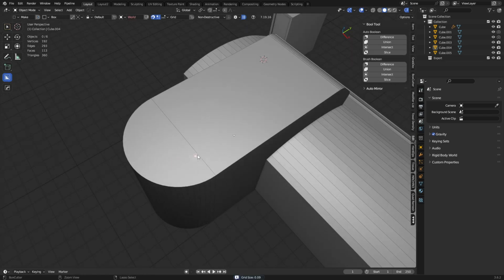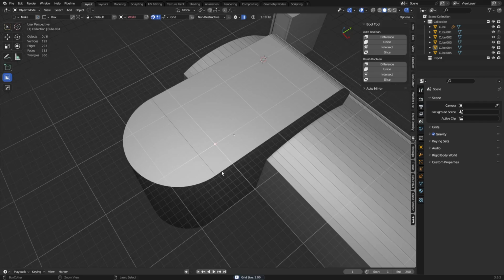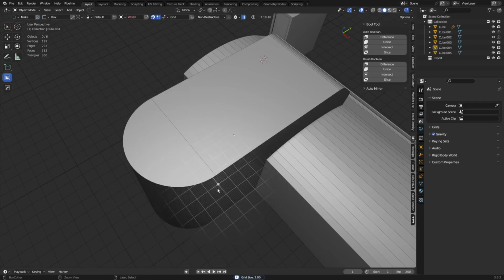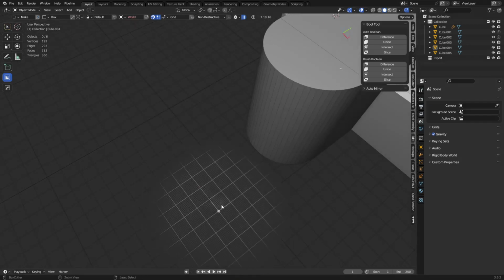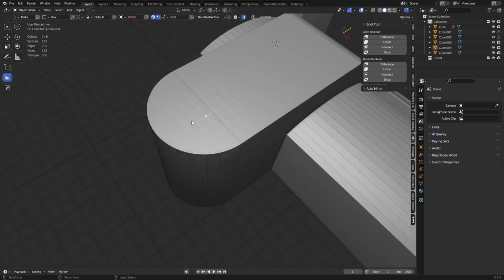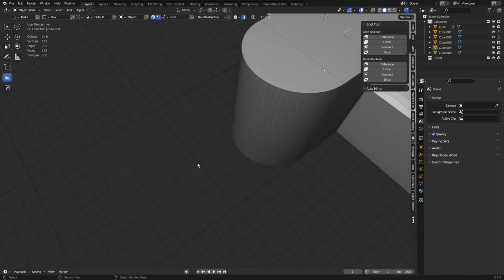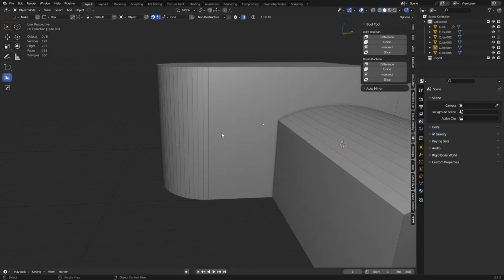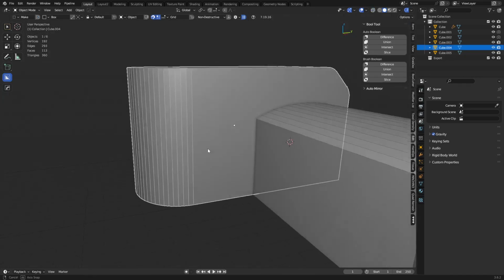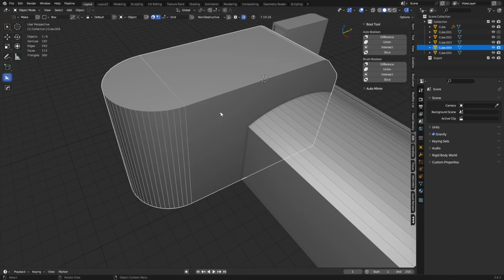And that is that the grid here has smaller grid sections, right? So if we set this to a grid size of 1, we already know it's going to match the grid of our scene. And so if we hold Control and Shift, we can snap every 10 centimeters, like we should be able to do with the add cube tool, in my opinion. But since we can do that with Box Cutter, you don't necessarily need to even see this grid. You can kind of understand what it's doing or how it's working potentially. The only problem you'll have is that if an object's origin point is not on the grid, it won't line up with anything else. So you want to make sure that's always correct.